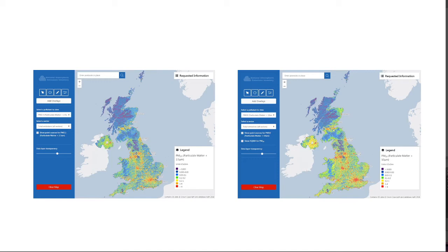So the design teams can therefore be better prepared to identify the minimum filtration efficiency required against a specific ISO 16890 filter group in order to achieve the designed supply air quality category or subcategory. The specification of a filter for a project in London is therefore different from one for a project in the Yorkshire Dales. But how exactly do we get to the minimum filtration efficiency required? A simplistic 5-step process is now proposed.